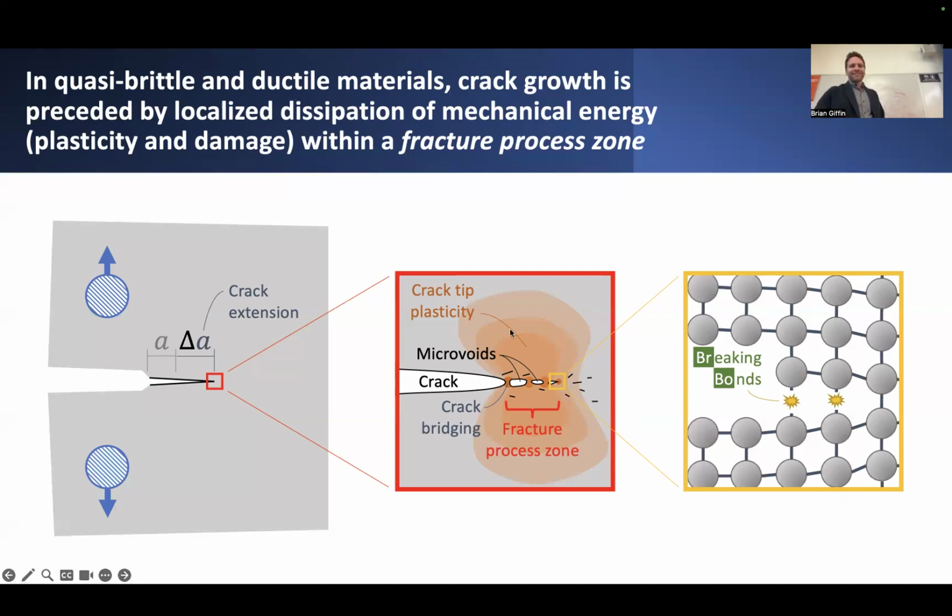And it really starts from plasticity to microcracking to microvoid growth and then void coalescence. But really at the smallest scales, it is still characteristic of bonds breaking in the material. So that's kind of the indication that obviously once the material fully separates, well, that's technically what we call fracture. But really at the mesoscale, there's a bunch of details that account for these mechanisms that govern fracture.